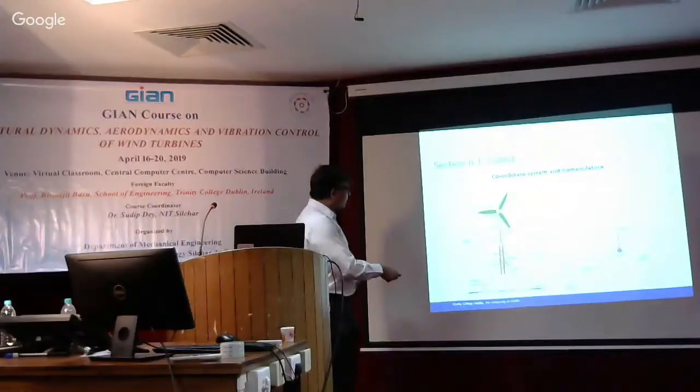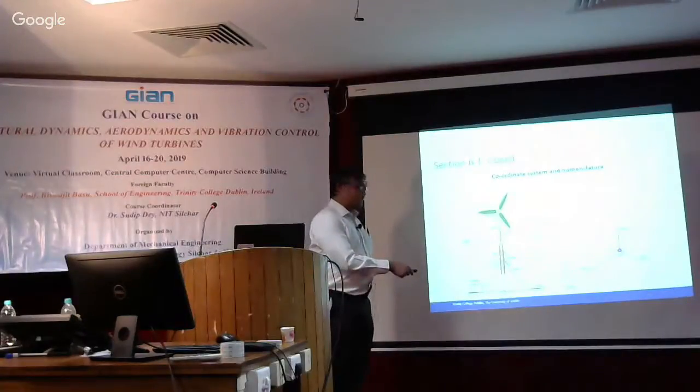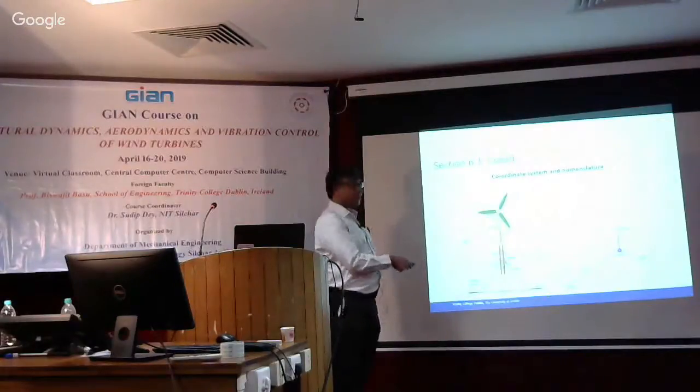And then you have to talk about the boundary condition at the seabed as well, because this is a flexible foundation. So it's an elastic foundation. So you can model this as a beam on elastic foundation. But also non-linear, because what will happen is there will sometimes be loss of contact. So that will actually lead to behavior like stick-slip and so on. That will also induce some kind of non-linear waves, which will propagate back.